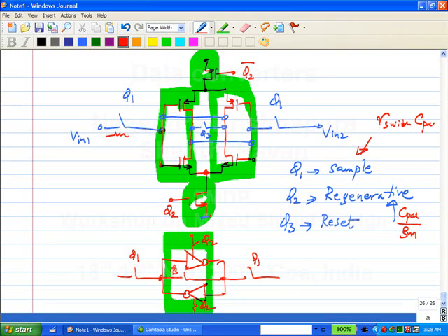Alright, often this is also called a latch. So obviously, it turns out that unfortunately, while this all sounds okay, in practice all these transistors will not be identical. So there will be mismatch which will cause some error in the threshold that you use.